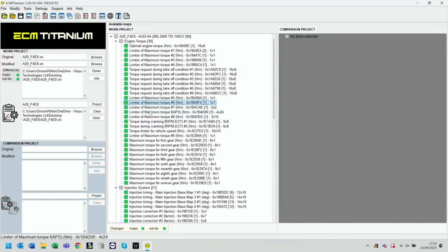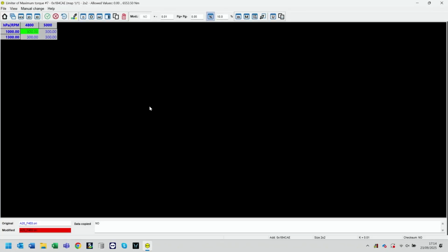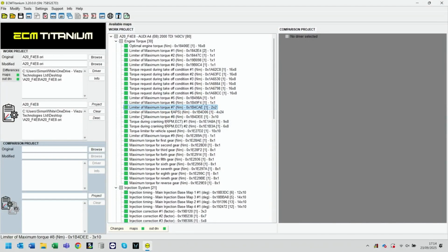You'll see in a number of ECUs, you won't often get the exact torque value in the table, but you'll have values that are either side of it, depending on how the map has been developed. What we're looking for is something that fits around those standard factory figures. Got you. Understood. We can see here we have 300 newton meters. So again, very important map for a specific reason, but not for what we're looking for.